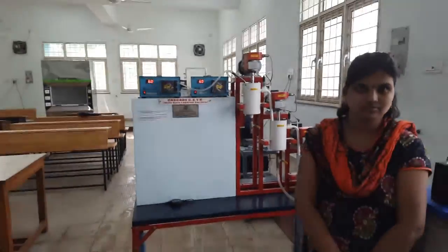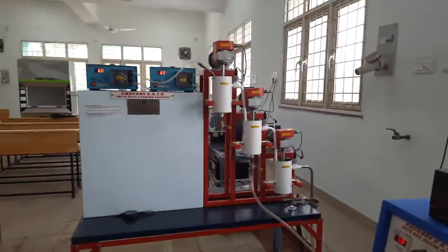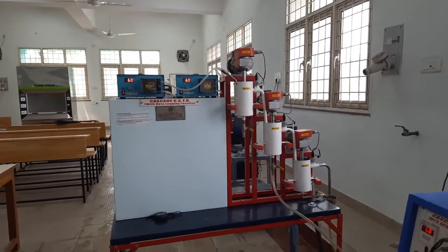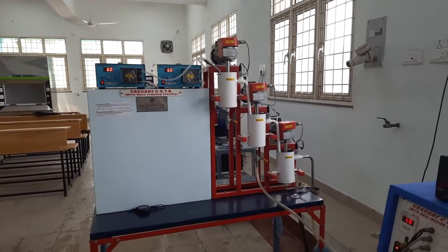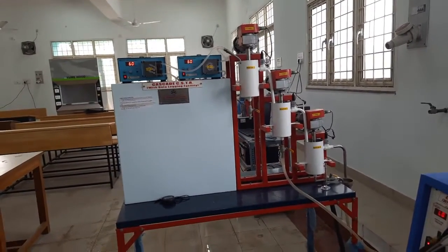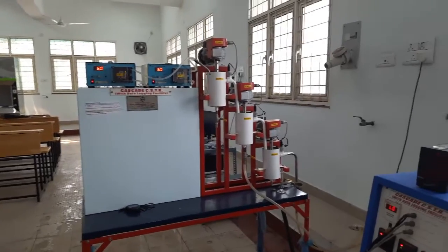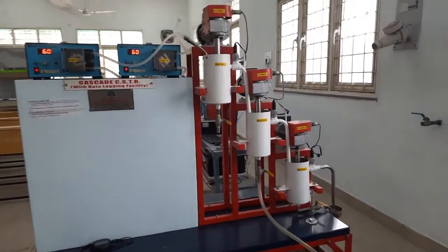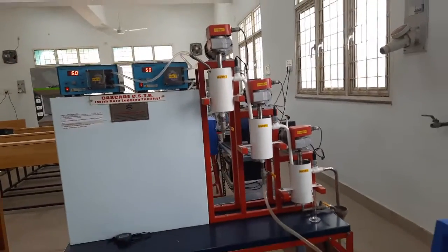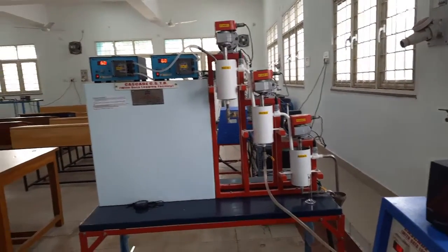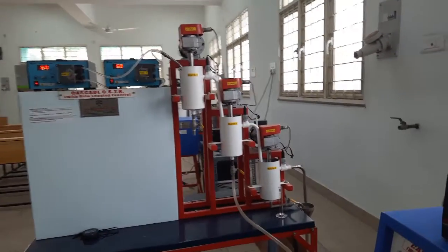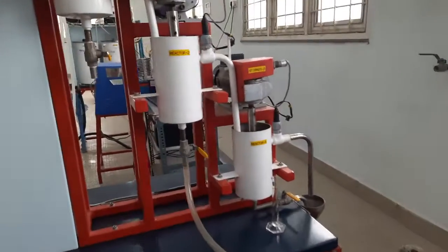We are only collecting the sample from the third reactor, but as an additional exercise, when you perform the experiment, you can collect samples from all three reactors after a certain time at steady state and see the conversion in each reactor. In that case we would do 3 titrations to know the intermediate conversion at reactor 1, reactor 2 and reactor 3. Now we are determining only the overall conversion at the end of the third reactor in this simple laboratory experiment.